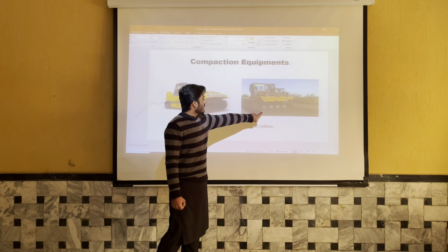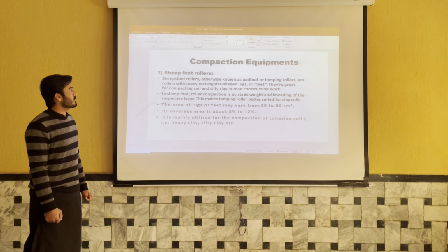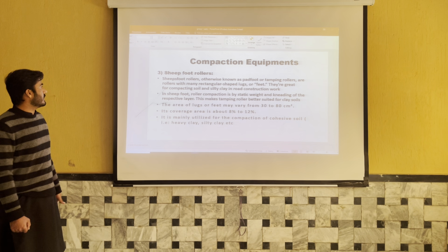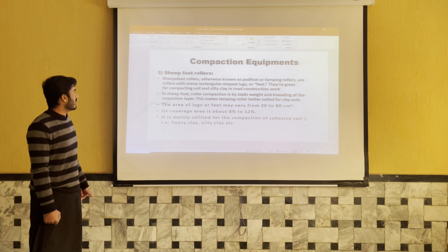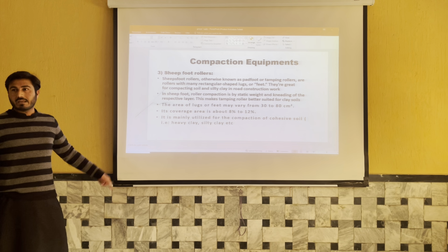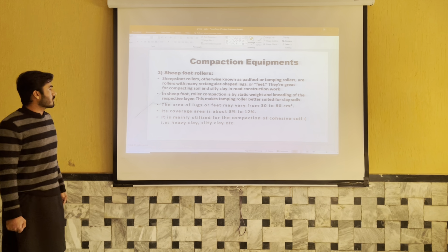Number 3 is sheep foot roller. Sheep foot rollers, otherwise known as pad foot or tamping rollers, are rollers with many rectangular-shaped legs or feet. They are great for compacting dense soils. Here actually there is a missing word: dense soils. Here should be dense soil, and silty clay in road construction work.